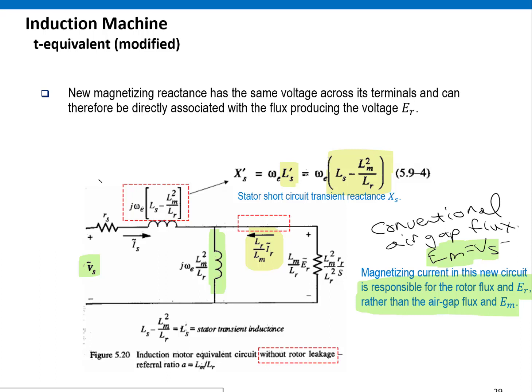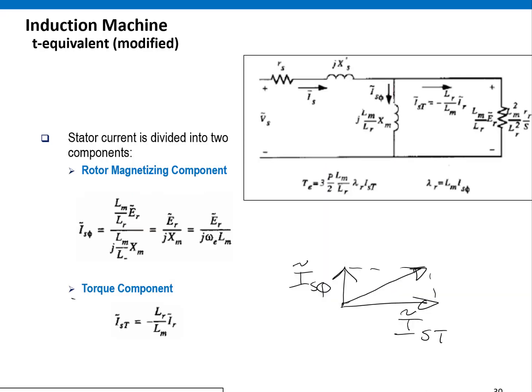That's the old way, but now with this change, it's going to say, well, let's instead use the magnetizing current to control the flux, the rotor flux. And the ER, which is proportional to the torque. So we've kind of created 2 degrees of capability, because we can then have these things aligning themselves in two directions along the imaginary axis in a phasor representation for the field flux, and then along the real axis for the torque. That's what we've got going on here.